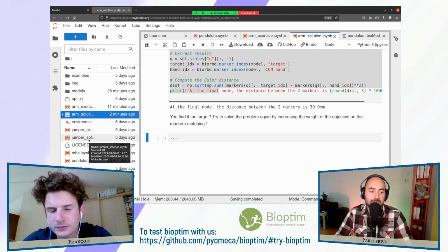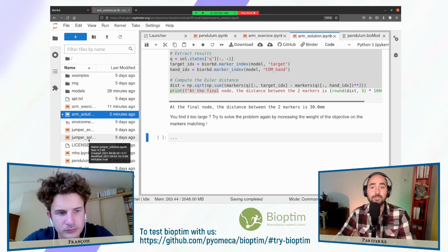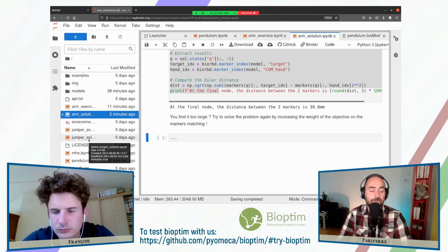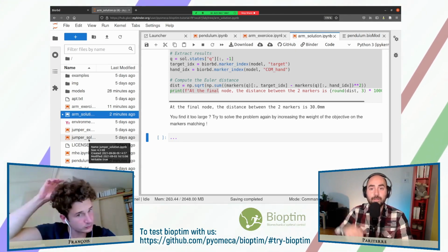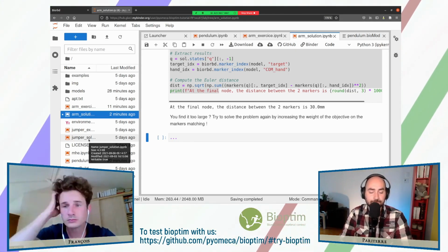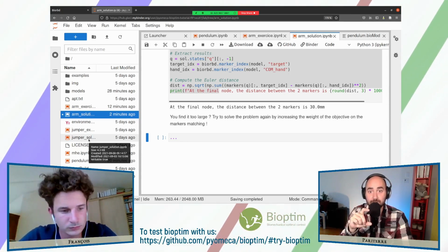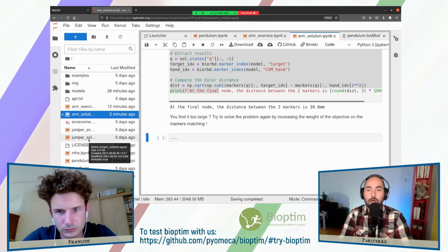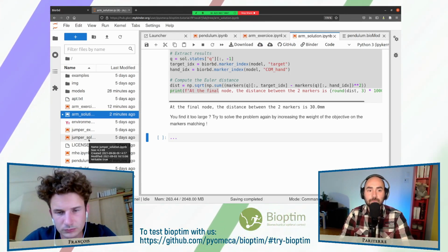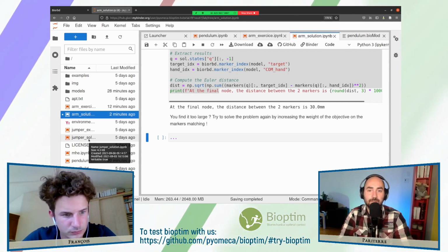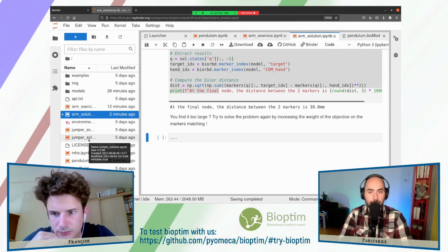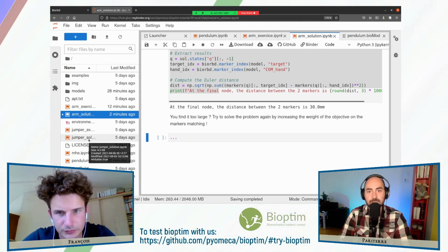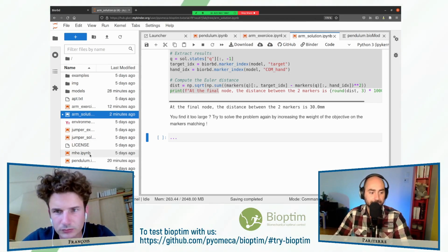The two remaining examples: the first is a multi-phase one. Multi-phase is when you change the dynamics of the system. For this example, we have a jumper. It has a phase where there's contact on the ground, and a free fall phase, and we show how to go from one to the other. So we have a multi-stage, multi-phase optimal control program. This won't work in Acados, though. Acados necessitates a single-phase program.